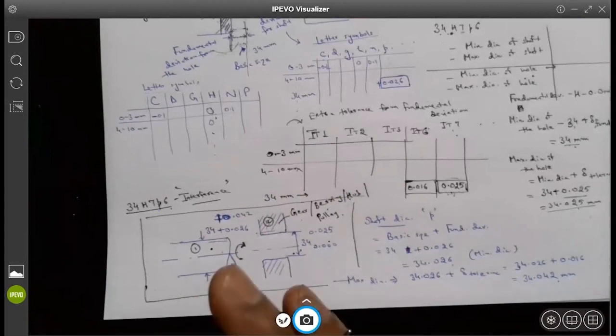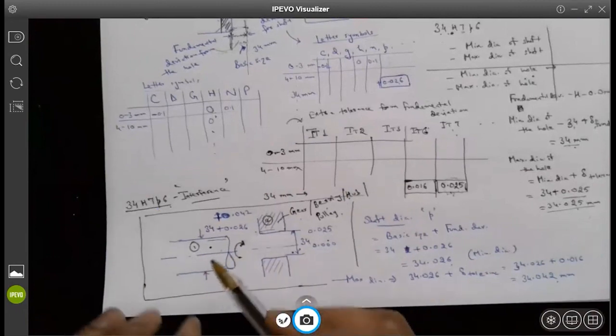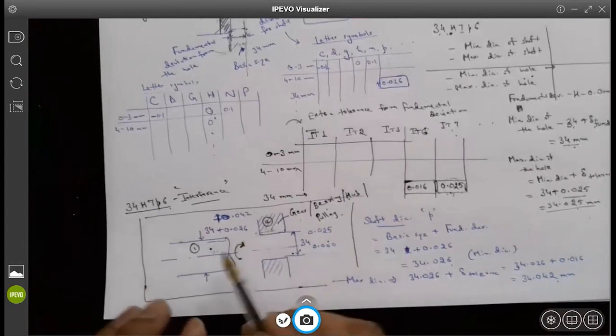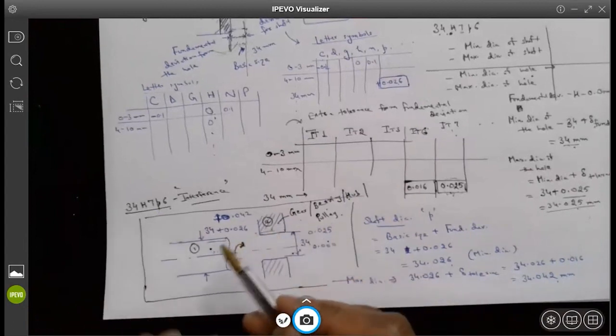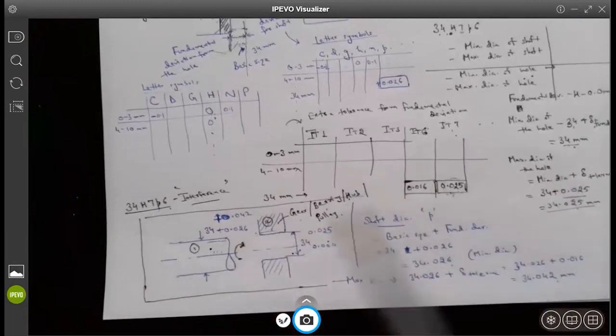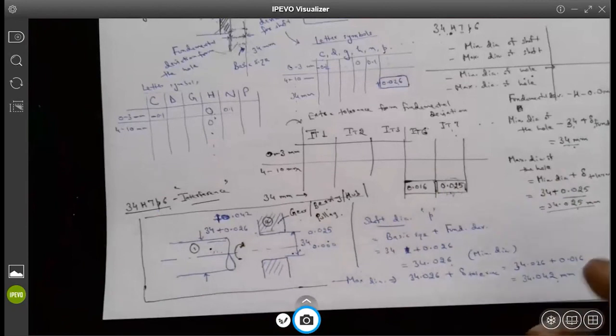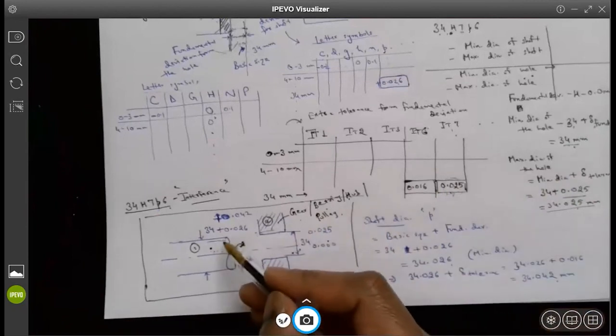Do you see what I'm saying here? Yes. The reason these two parts can be assembled together is that if they are rigid, they can never be assembled. But every material you can think of, whether it is aluminum, steel, brass, copper, has a specific elastic modulus. It means that it will elastically deform.